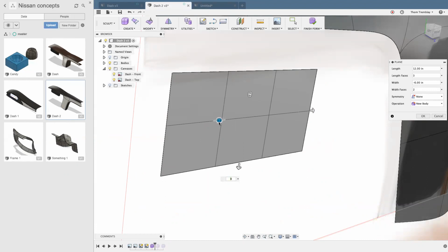When you use the face tool, it just creates that single face. So I could have easily started out by creating a plane for that initial shape and then just edited the edges. There are just different times where you feel like you want to get a certain start and you can start beginning that way.